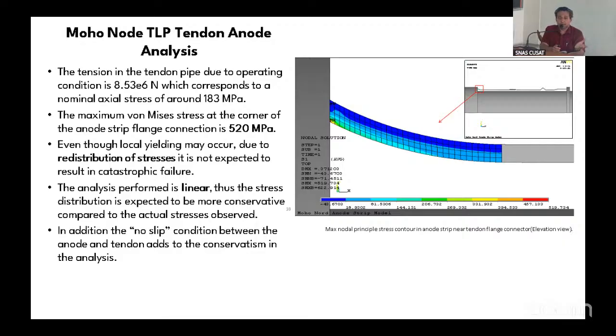Sometimes, I was doing a riser analysis once, and there were compressive stresses at the bottom. Risers are extremely tough to design, because it's essentially just a pipe. With structures you can actually add things, but if you have a pipe, there's only so much you can change: the wall thickness, the diameter. There's nothing much you can change. I had compressive stresses, but I was able to convince the client. We did some statistical tests, and we were able to convince the client that it is not going to be a problem.